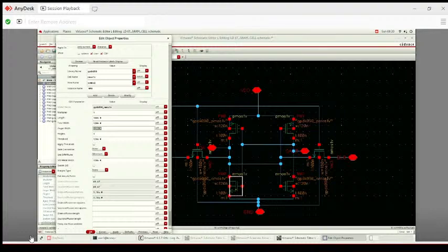If we don't follow the standard sizing rules, then our SRAM will not operate properly. Maybe read or write operation will face some issue. That's why we have to keep focusing on this sizing while designing an SRAM cell. Let's set the sizing of both NMOS or pull down transistors to 270 nanometer. Okay, remove the one. So yeah, 270 nanometer is set. So let's set the similar sizing for the other pull down or NMOS transistor. It's also 270 nanometer. Okay, the width is set.